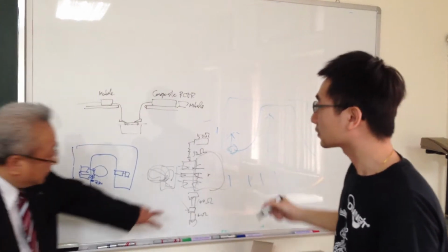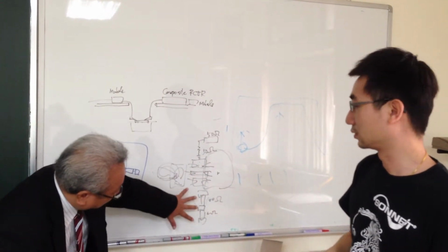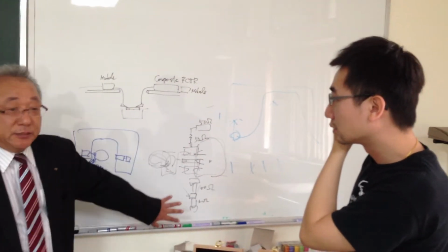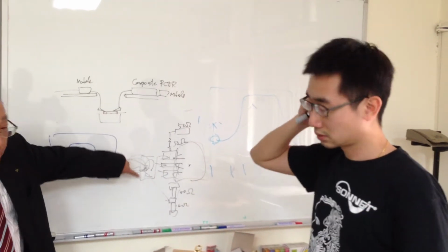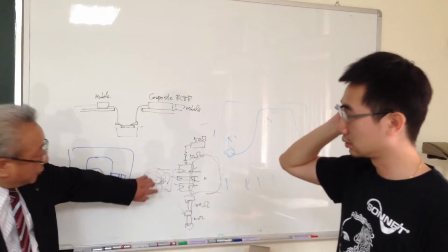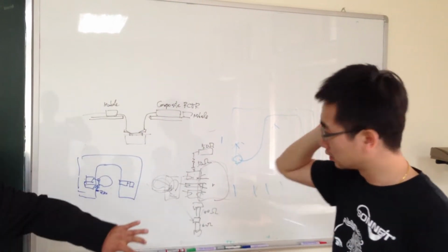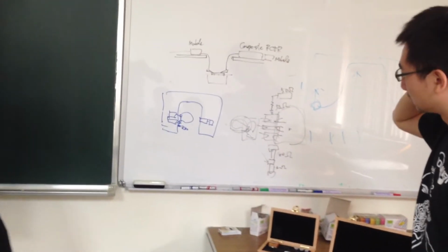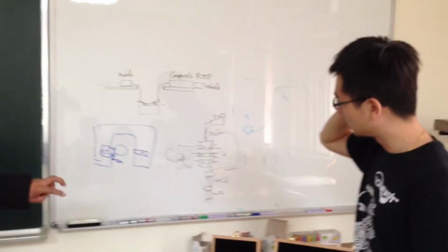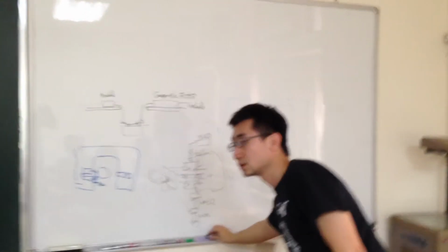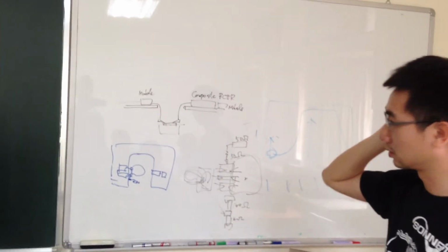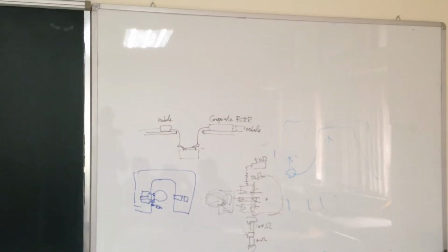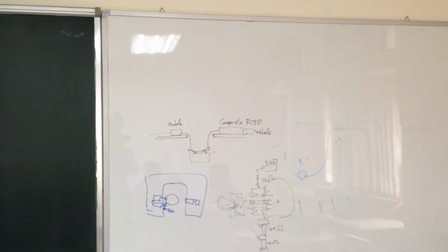Yeah, this is like 100 ohm, 100 ohm. The calculated value is 50 ohm in series, but there is some mismatch. And if they're using the partial type of termination here, and they're using the 50 ohm through line, sometimes it is more accurate. No, that is 190. So we have to check which is better for the loss factor or something like that. And also right now we are working on the de-embedding and embedding for the on wafer measurement.